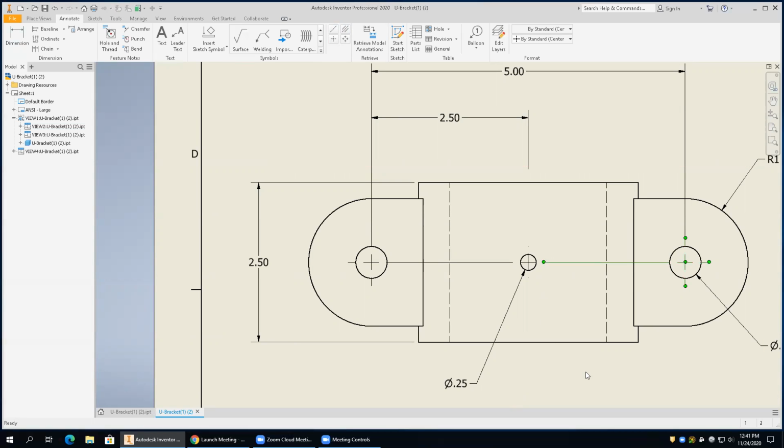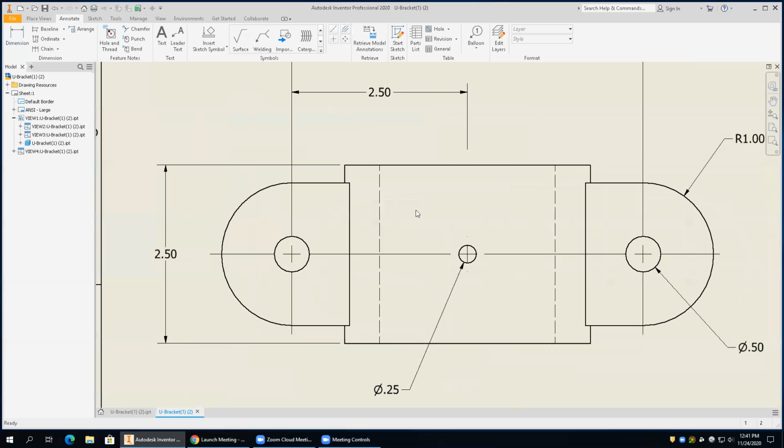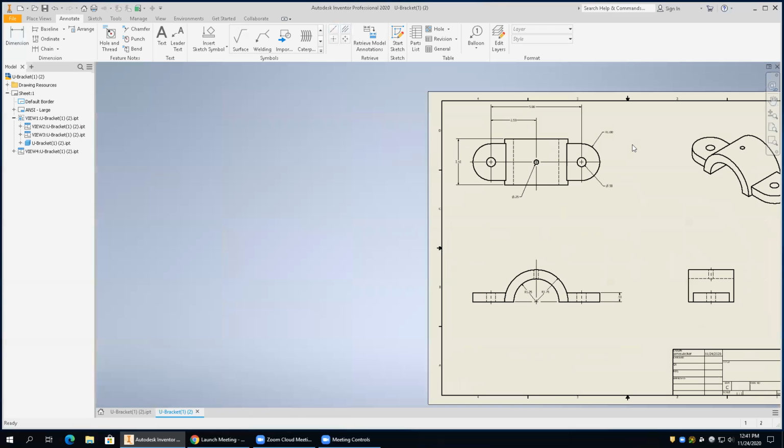Now, depending on the discipline, a lot of times you would take this guy down, maybe go a little bit that way to the tangent, past the arc. And I could pop that one up if I wanted to. I don't really need to do that. I can do the same thing over here. Just drag that and drag that. Okay. So technically everything's good. I would probably want to drag this guy up till he touches that and this guy down because that's really the center mark of that. So that would be a proper configuration of using center marks in your bisector lines.